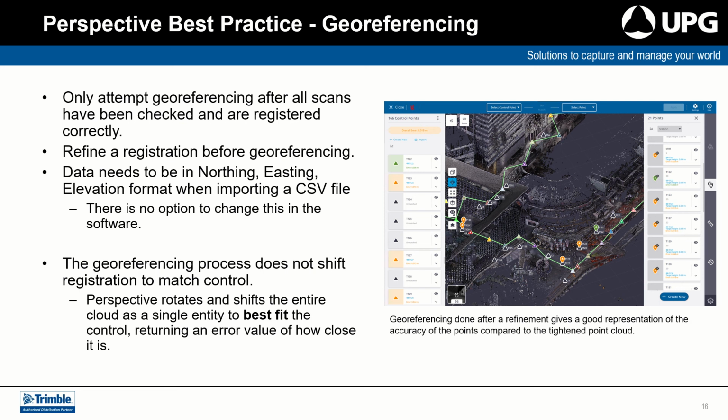And it's worth picking up particular points in the scan data as you go through to make sure that there are annotations or notes against them to make them easily identifiable later on. If this can't be done, say where the corner of the building has been measured using a total station and you have scan data that you're trying to match up to, it is worth taking some form of note down to pass on with the scan data, as you may not necessarily be processing the data yourself.